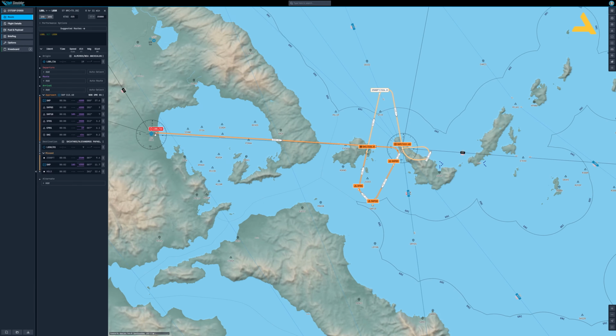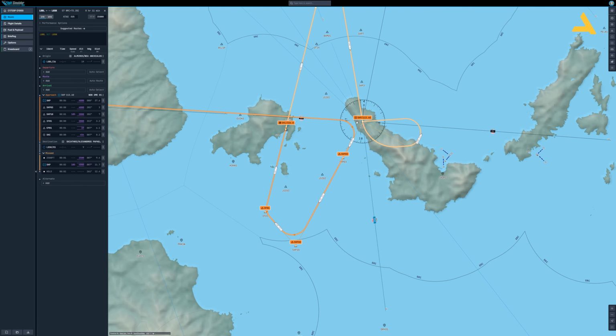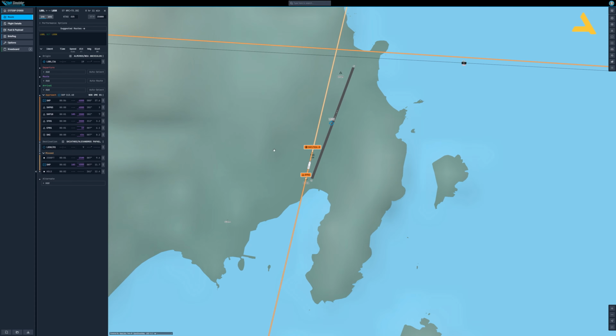So now in this case, you will fly from this airport. You will fly on heading 88 degrees by tracking this VOR. And by the time you're near this VOR, you turn right, 202 degrees. You can keep on flying it. This is 3 nautical miles at this point. And further, you will travel 7 nautical miles before you turn right. So this is a total distance of 10 nautical miles. You will travel like this. Then you will turn right, heading 313. And then from here, you will start tracking the NDB.